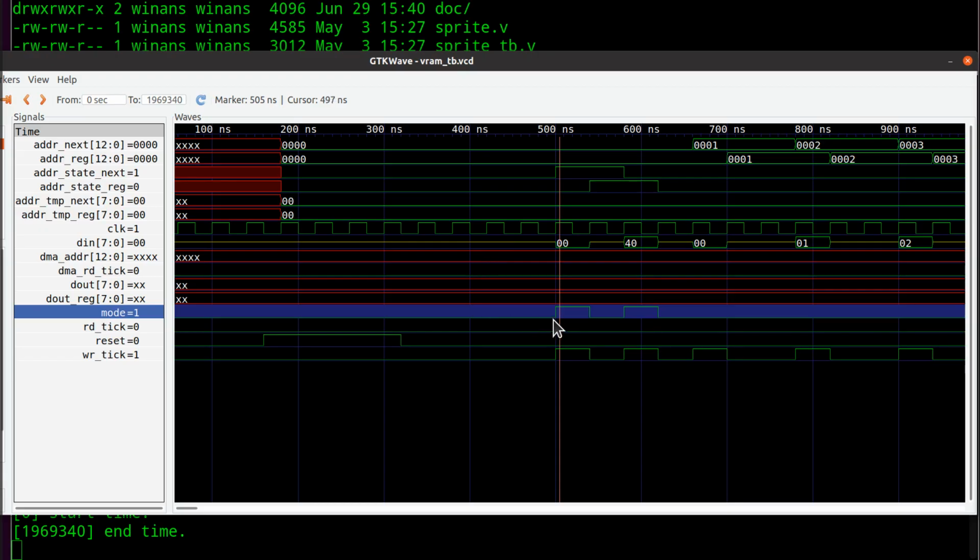After that, this became high, and it stays high and goes low after this goes high. So be careful how you read these waveforms. This is the setup time for that leading edge there. Just because it looks like it's high at the same time as this one, it's not. This one goes up an infinitesimally small amount of time after the leading edge on the clock. So this is true here.